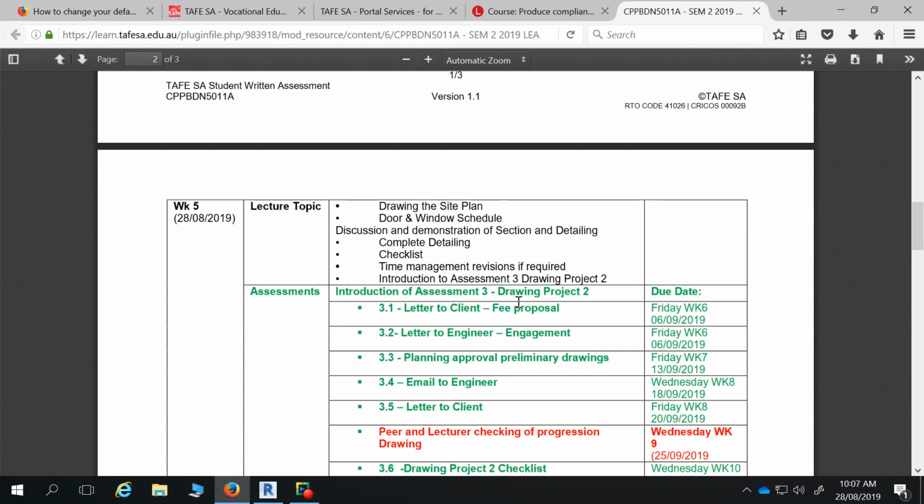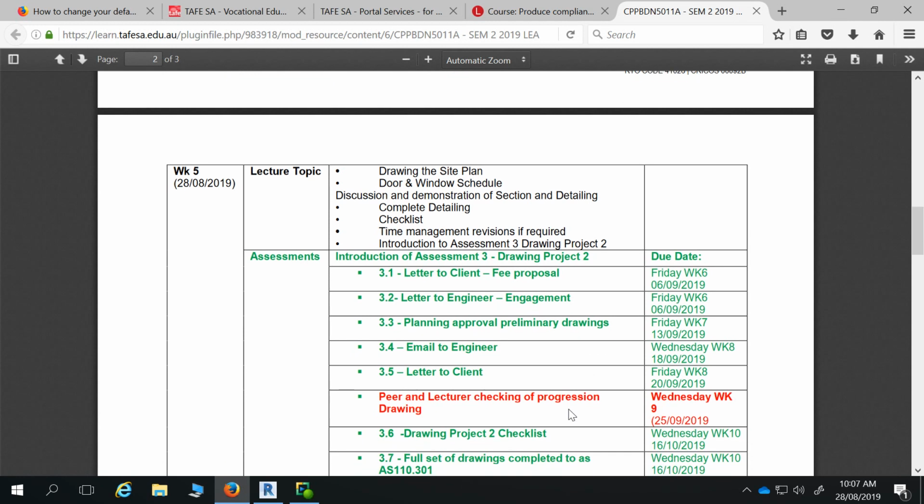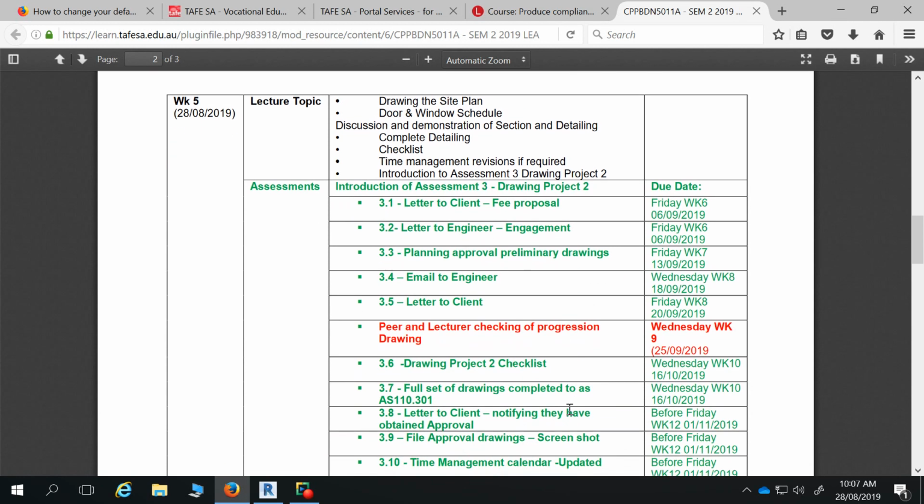So just show your window schedule and door schedule, and whatever columns you feel are appropriate for this. I wouldn't worry about suggesting double glaze for this little one, because we haven't gone down that route at this stage. But usually that's where you would show which ones are which. It might be the case that some aren't double glazed, and some might just have some low E coating. There can be so many variants with doors and windows, so that's why the schedule makes it a lot easier to populate that information.